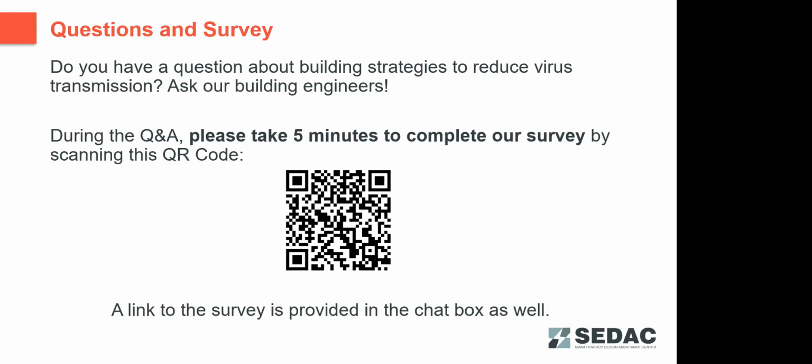So I just wanted to mention to the audience that, as you were showing the extra costs for increased ventilation and potentially for filtration and other things, those numbers like 10,000 CFM, that's enough for 250 to 500 students. And so a potential increase in blower power really comes down to about 50 cents a student. If you look at what that cost is per student, it really isn't significant and is well worth it, as you mentioned, as far as the health.